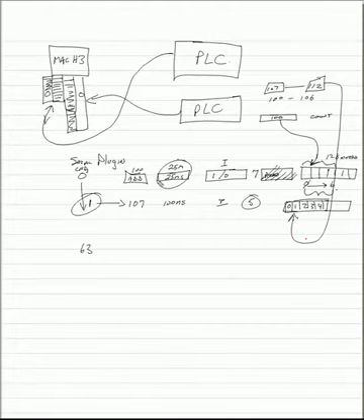The same thing works in reverse. Say we set configuration area number 5 to start at address 120 and to go every 25 milliseconds with output for 5 registers.